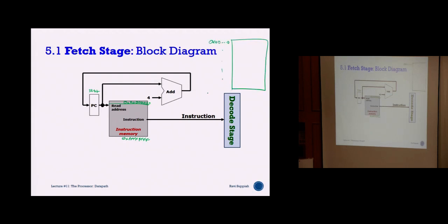I've drawn this before. If you look at your memory design, who does the memory design? The system architect, correct? The system architect must decide: for this processor, I have a 32-bit bus, so this is my address range. For this address range, where do I keep all my subsystems? In most cases, your instruction memory, if you're talking about a standalone system, will start from address 0.